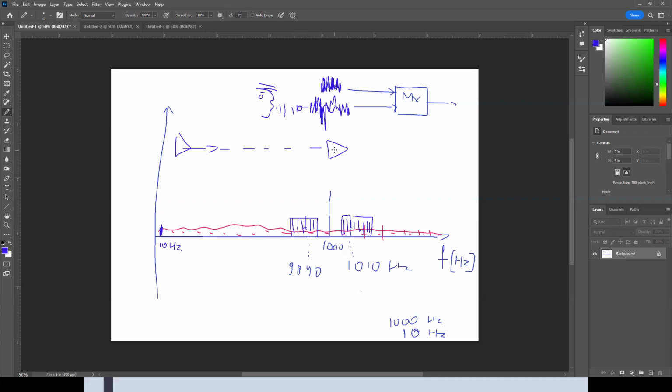Then all we have to do is tune to this frequency, the carrier frequency, and at the demodulating stage of the receiver, all we have to do is strip away the carrier, because we don't need that at further stages, and just keep the intelligence signal. So we have a voice coming in here, and the voice is going to meet the carrier, and it's going to alter the carrier, is going to affect the carrier in a certain way, and we're going to call that modulating. So it's going to modulate the carrier.